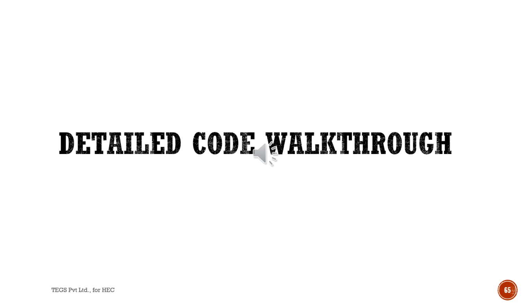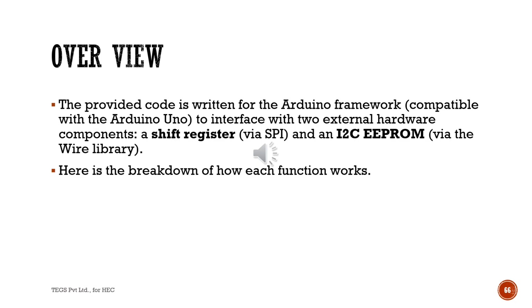Method 8. A detailed walkthrough. Overview. The provided code is written for the Arduino framework, compatible with Arduino Uno, to interface with 2 external hardware components: a shift register via SPI and an I2C EEPROM via the Wire library. Here is the breakdown of how each function works.